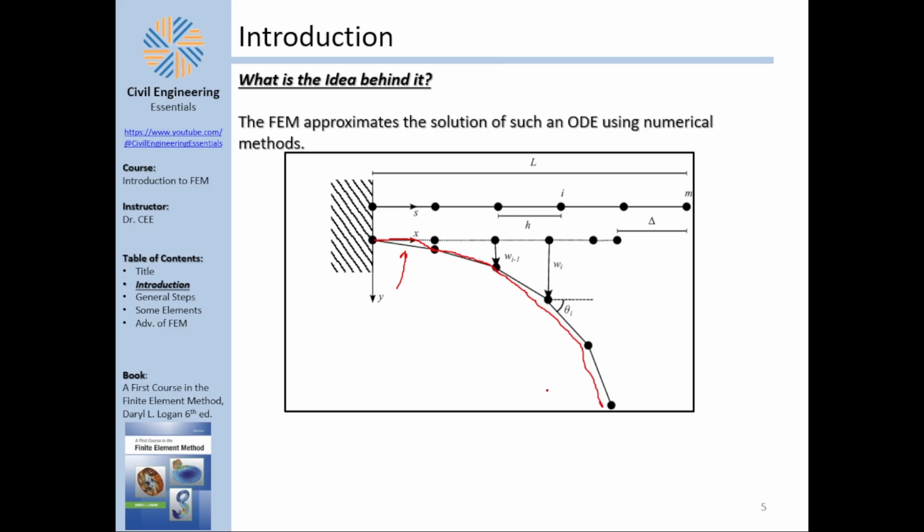Now, this is something we call P refinement: instead of adding more nodes, you can improve the deflection approximation between 2 adjacent points. Have you ever done this before? Well, outside the finite element, yes, you have done this in something called the Simpson's 1/3 rule versus the trapezoid rule when you were approximating integrations.